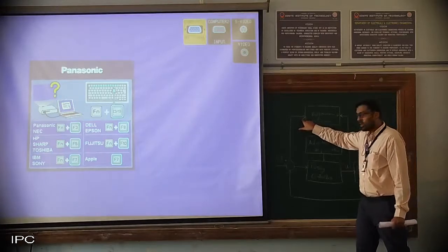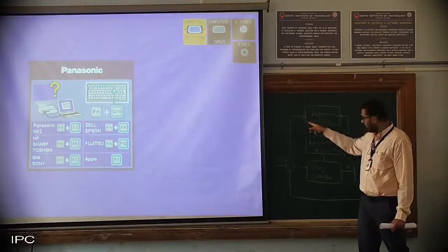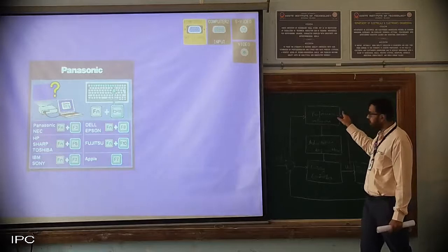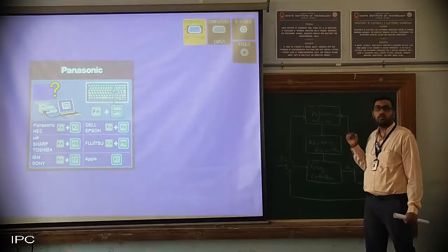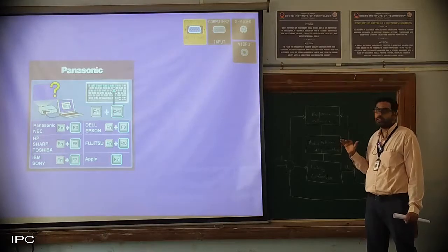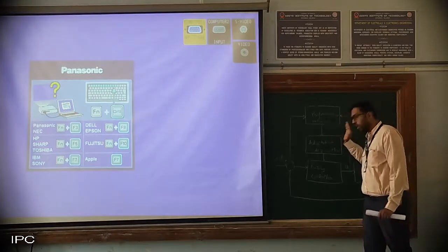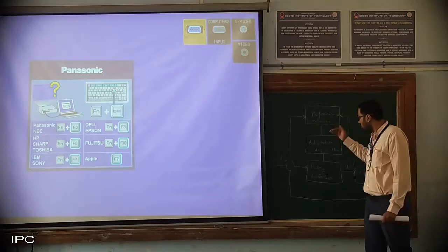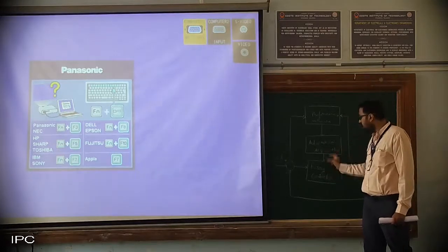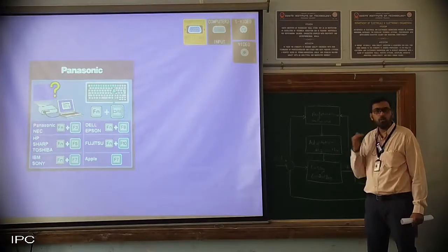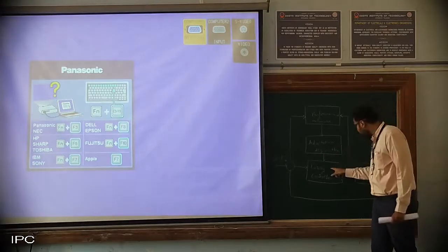But your requirement was how much? Increase by 20, but we have got 18. So what is the performance? Again there is an error of 2. So the performance is not 100% yet. So again the adaptive algorithm will come into the picture. It will tune the functions and again give the command to the controller that you need to increase the value by another 2 RPM.